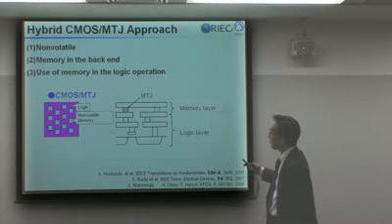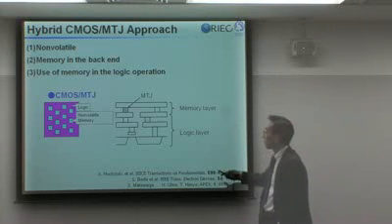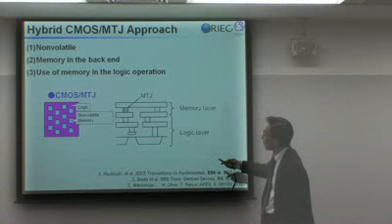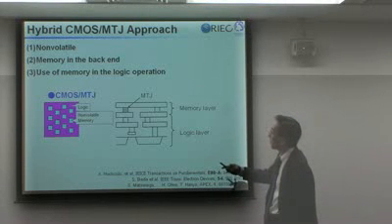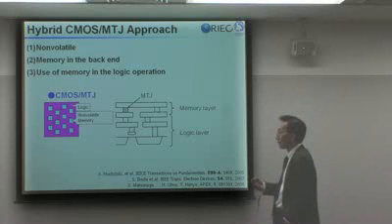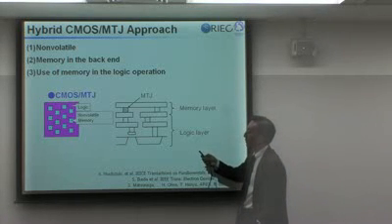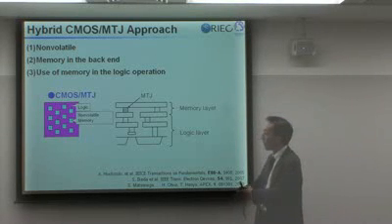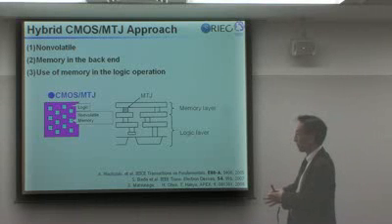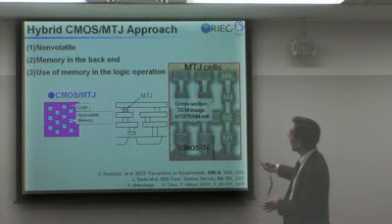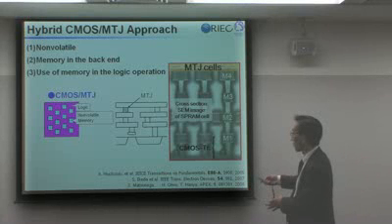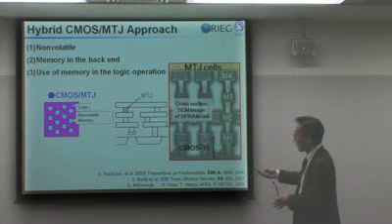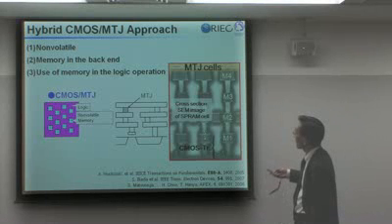And actually, when you come up with a very good circuit design, you can actually use this magnetic tunnel junction to do the processing. And that means that you can even reduce the number of transistors to do the same function. And that again gives you, you can do the same thing with less area and fewer transistors and less power, and it's very cost effective. And this is just a cross-section of our CMOS transistors with interconnection, and our magnetic tunnel junctions are sitting here.